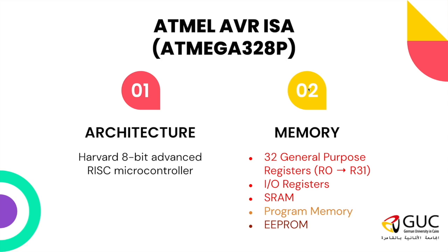Finally, it is a microcontroller, not a microprocessor. If you remember the difference between microprocessors and microcontrollers: if I have a chip, it will be called a microprocessor if the entire chip is occupied by the CPU and computing components. However, if I want to connect a memory to a microprocessor, I need to connect it externally. I do not have a memory or I/O peripherals inside the microprocessor chip.